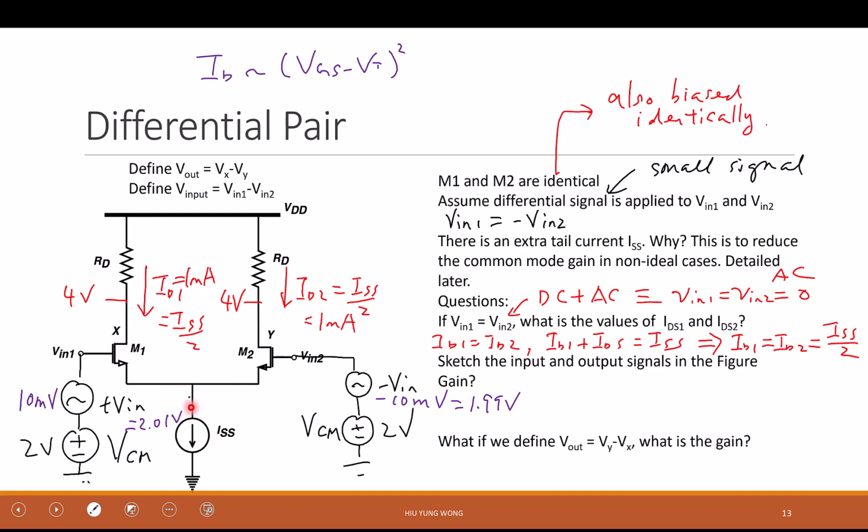So this is going to change this point. But as you said, when the gate voltage on the left increases, then maybe this one will add, for example, 10 microampere, and this one will subtract 10 microampere. What do you mean by proportional? They need to change by the same amount, so that when you add them together, they are still 2 milliampere. Okay, have this concept: if the left increases, the right needs to decrease.